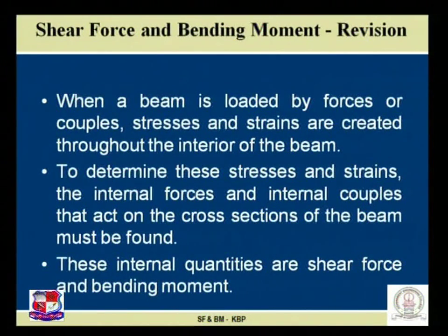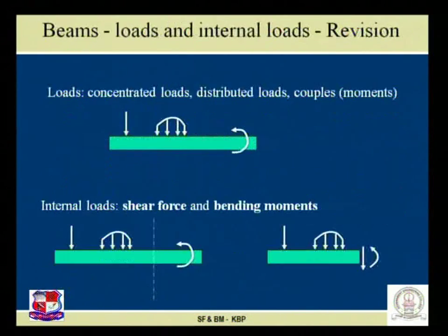Let us clear out our fundamentals. So, what is shear force and bending moment? When a beam is loaded by forces or couples, stresses and strains are created throughout the interior of the beam. These internal quantities are referred to as shear force and bending moment. Let us understand by using a simple beam. This is a given beam with application of external loading.